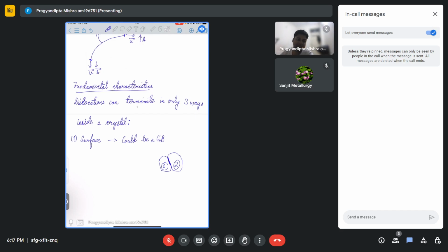So this also forms a surface, right? Because that is the surface where your crystal 1 ends and crystal 2 begins. So that also represents a surface. Now this grain boundary essentially is formed when the crystal grows in a particular way. When you heat the crystal and start cooling it down, grain boundaries are formed. We will discuss how these grain boundaries are formed in the later weeks when we discuss grain boundaries as a defect. But yeah, grain boundary can also form a surface. So there can be surfaces in different ways.